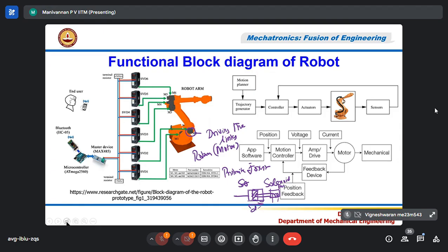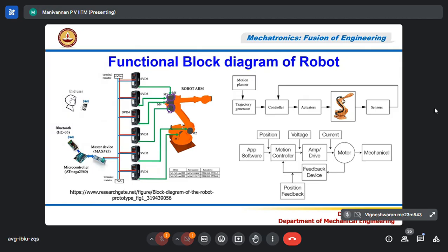So in this robot, you have a mechanical structure made of joints and links. Then you have motors, because this is a 6 degree of freedom robot having 6 rotary joints. So that means 6 motors are there, M1 to M6. When I want to move the end effector, by moving the joints, the position of the end effector with respect to the XYZ axes in 3-dimensional space changes by moving these 6 motors. That is what we call kinematic equation or analysis.